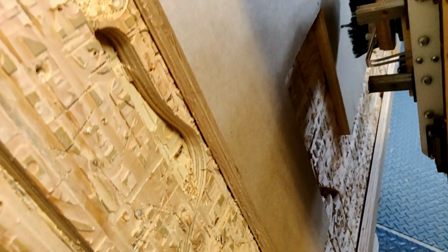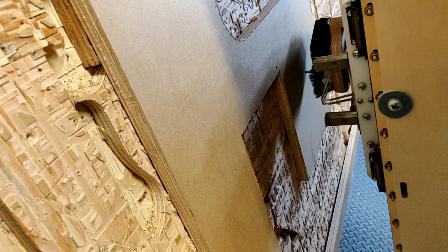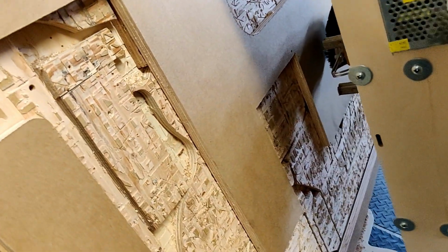If you have a pretty flat surface, then it doesn't really matter where you zero the Z. But if your surface isn't that flat, maybe the workpiece is warped a little bit, you'll have that happen on very large pieces, you might want to go to the lowest point or go to the center of that workpiece. Okay, so I'm going to put it to step, and I'm going to lower it incrementally.